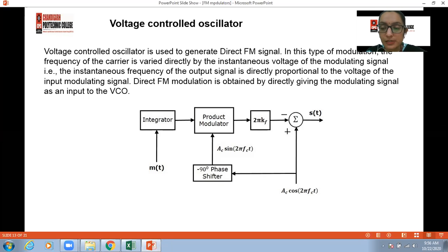We will discuss this in the next topic, that is our stabilized reactance modulator. Here the output of the generator is applied to the mixer together with the output of a crystal controlled oscillator, and a difference frequency term is obtained. The mixer output is then applied to the frequency discriminator, and after that it finally goes out to a low pass filter.